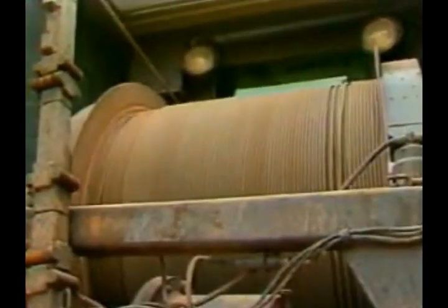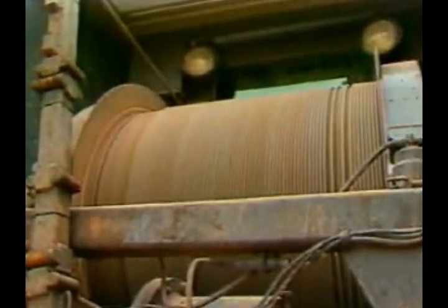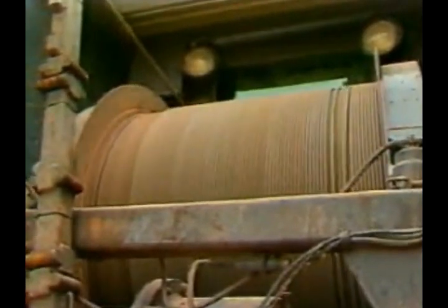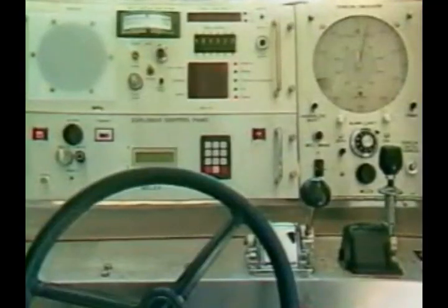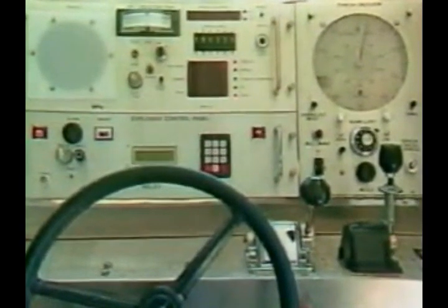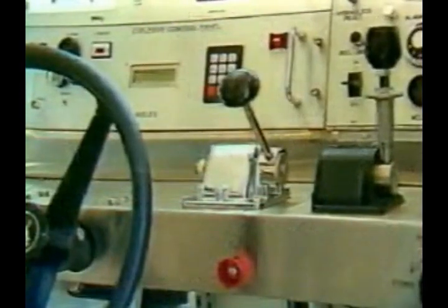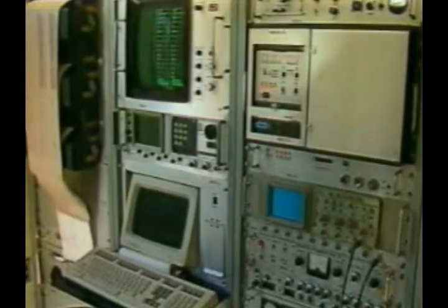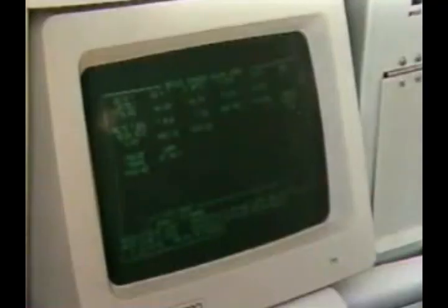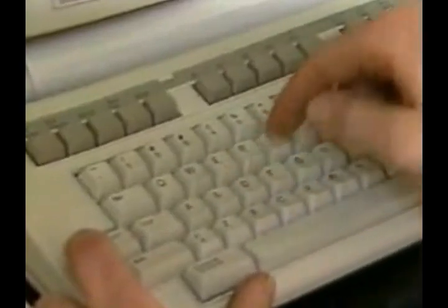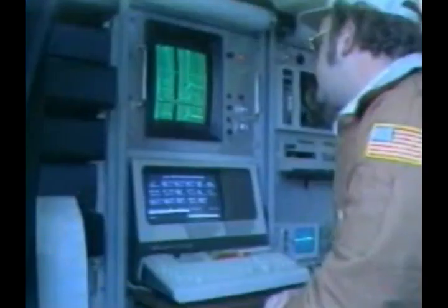The winch mechanism is used to lower and raise the cable and attached logging or sampling tools into the well bore. A winch control panel measures the amount of tension on the cable and operates the winch at optimum speeds for various logging tools. Also, the tools can be positioned at precise depths for necessary tests and measurements. The computer is vital for receiving, viewing, and adjusting downhole tool responses, for storing and manipulating data, and for recording field logs.